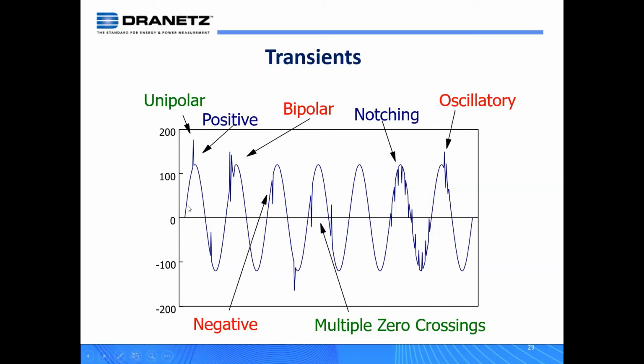right over here, okay? I have another one, another one, another one here, but you see, I counted an extra here. I counted an extra here. So if I'm counting time, certainly here in the United States, 60 hertz works out well for time. I've just counted 2 more clock pulses here. So my circuitry is going to miscount because of these transients. It sounds basic, but it still is a real problem.